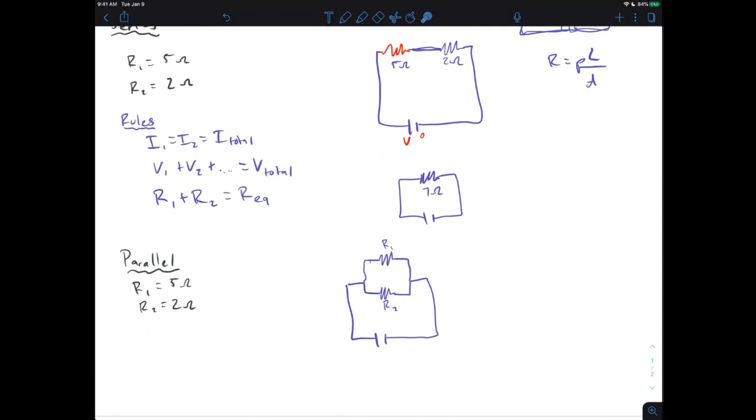So this is, you know, you could keep opening up essentially more lanes in the highway. Your current's trying to get from work back home. And then even if you have more resistors here, you have more lanes, so you're still going to get more current flow. So it's weird because I can keep adding more resistors in this way, but my resistance will actually keep slowly going down. It'll go down, down, down, down, down, instead of going up. Because in each of these cases now, if I add more resistors, my current has more chances to squeeze through somewhere, right?